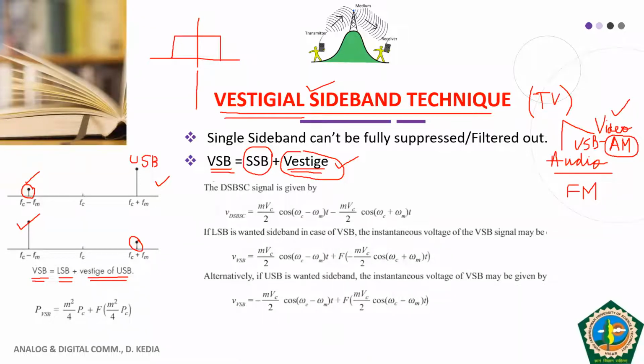Whereas practically we are not able to have an ideal filter, so our response looks like this. This is our practical filter. If we had an ideal filter, we could attenuate our signal at this frequency range, but it's not possible. That's why, apart from whatever range we want through the filter, some additional part is also coming into the picture, and we have to bear with this additional part, because practically in no case can we have an ideal filter. We have to survive with a non-ideal filter only.